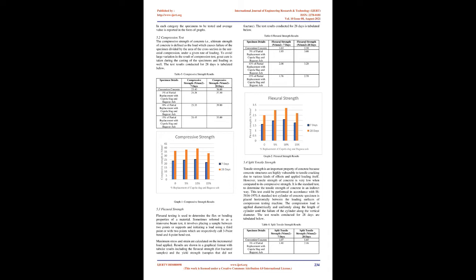There is one slag hole from which slag comes out at higher temperature with low viscosity that solidifies in black-colored lumps upon cooling. Lump size varied from 100 mm to 450 mm. Cupola slag tends to be dense solid material that varies in color from gray to black. A physical property of cupola slags to be used is compared with natural coarse aggregates and IS 383-1970 requirements for material to be used as aggregates.